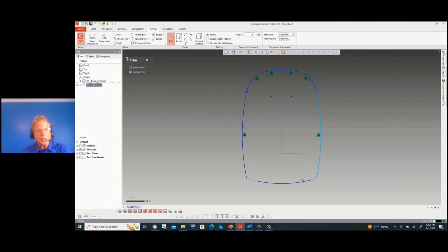We'll just trim up these edges to get a fully enclosed model. Then we'll exit the trimming tool. We'll jump into our smart dimension tool and start building some more design intent into the model.